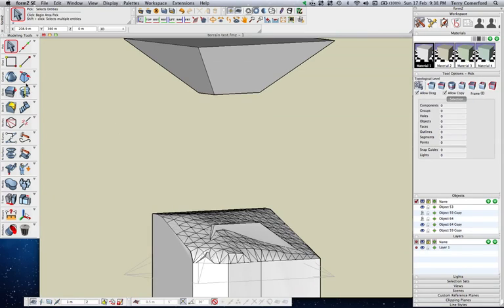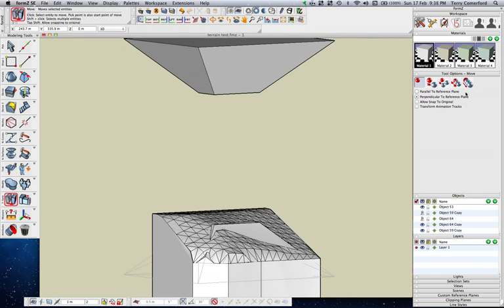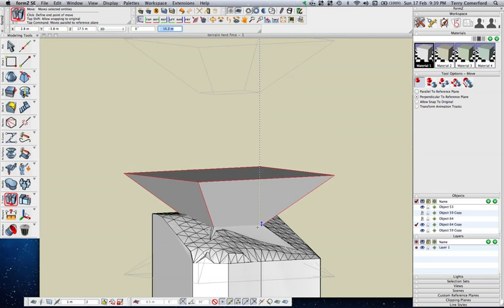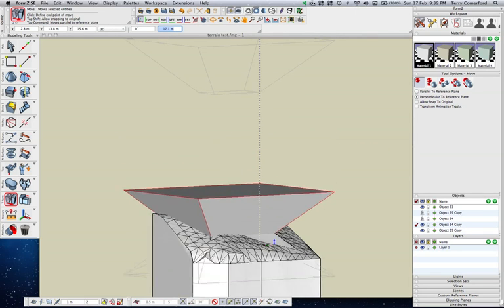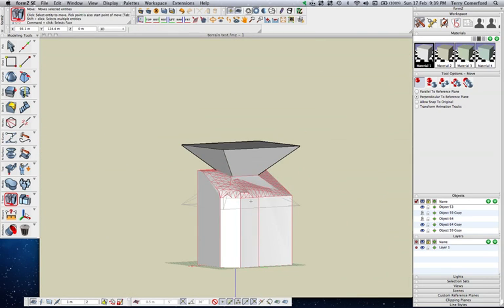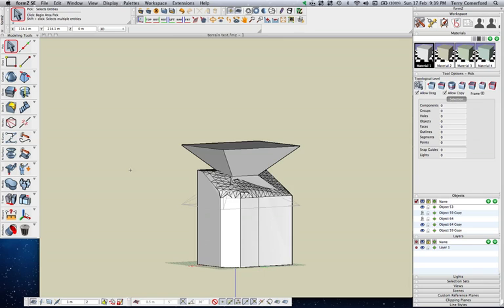Okay, so I should now be able to transform move that object perpendicular reference plane. Might try, and this Ghostbusters sign for error snaps, so I think I'll turn that back off now so I can actually snap from that point, and take that point down carefully down to its mating point down here. Okay, so I've got these two different solids.